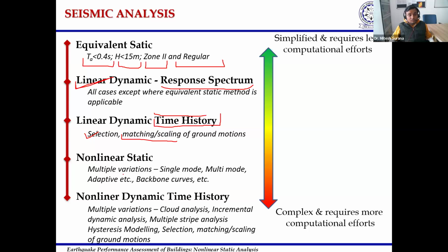There are different varieties of the loading pattern that are being recommended in literature, that can include the loading proportional to fundamental mode, that is called single mode based pushover analysis. Then there can be loading based on combination of multiple modes, and that is called multi-mode pushover analysis. Then there can be adaptive type of loading. Adaptive loading means the loading which changes with each instant of time while we are applying the monotonically increasing load.